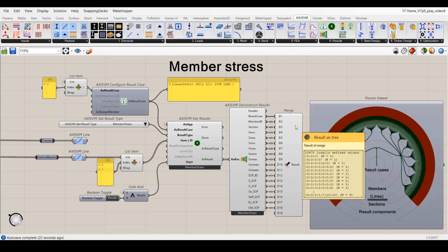that the lines expression is in brackets on the param viewer because that intermediate path is not really a part of the data tree. You can see that I don't have any branch path with 5 indices, but the 5th index of the section paths is growing from 0 to 7 to group the sections according to the finite element mesh.